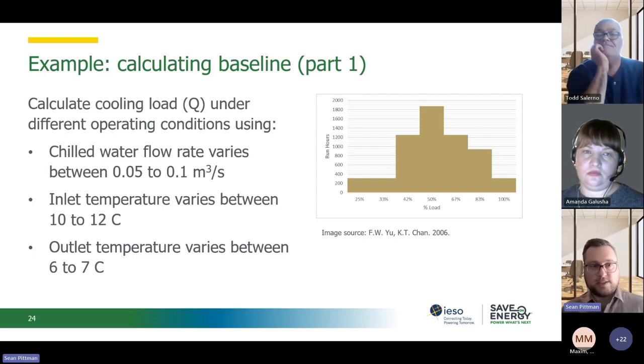I would say on the very simple end, if you have a measured period, you could apply that as a ratio across the year. So if you measure for a month, you develop a similar graph like this that only covers a month of time, and you apply those percentages to 8760, and that's how you extrapolate that one month to a year. If you think your load is fairly consistent month to month, that might not be a bad approach.